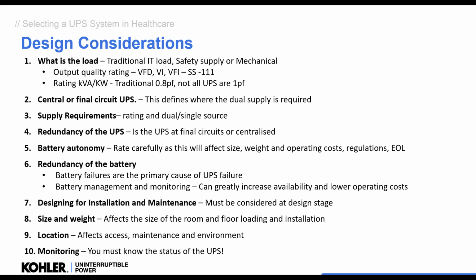Redundancy of the battery does talk about having secondary strings or parallel strings. This is for maintenance, redundancy, and if we monitor and manage it, we can actually make that battery a very, very resilient system. Make sure we design the system for installation and maintenance. This is not always done. Many UPSs are stuck in a cupboard with no thought for the ongoing maintenance.